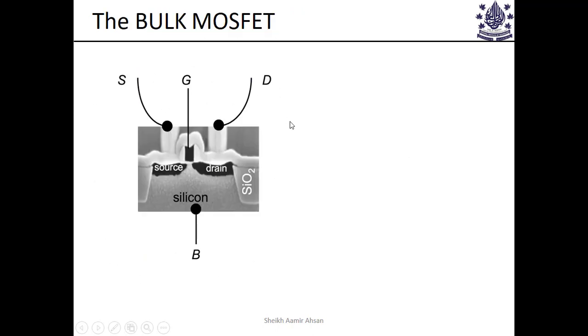Now, in the previous slide, I showed you a simple cartoon of a MOSFET. That is not how a MOSFET actually looks in reality. This is a zoomed SEM or TEM picture of a MOSFET taken from Texas Instruments. You see that these structures do not have nice, well-behaved corners and perfect shapes. You may have slight deformations or some tapering somewhere in the structure, and that is how these things are in reality, and that's why you see some more real effects.